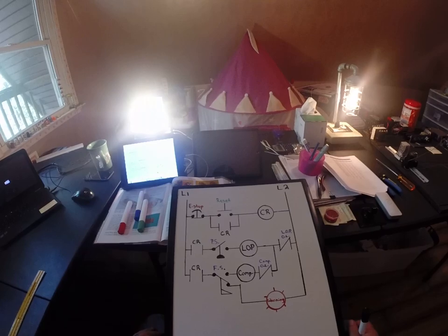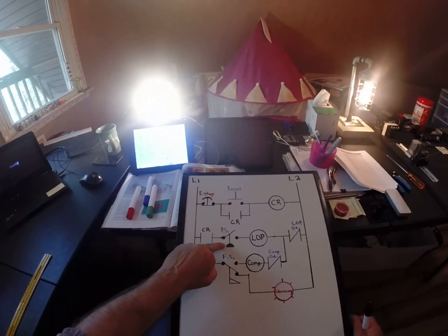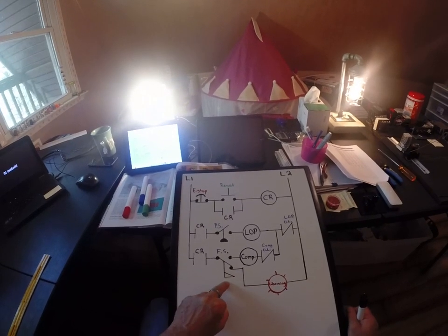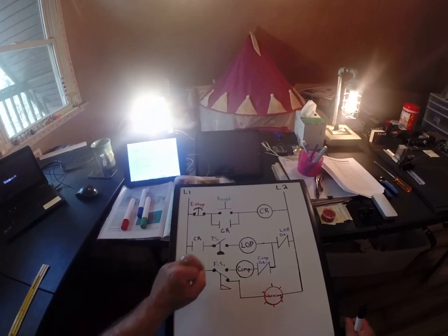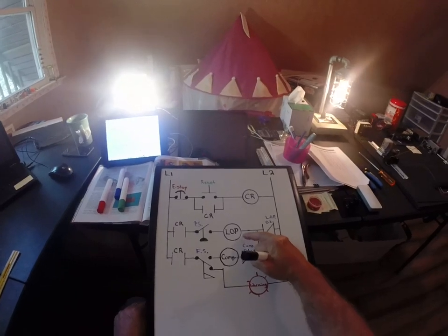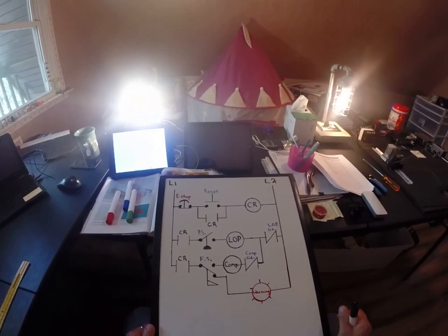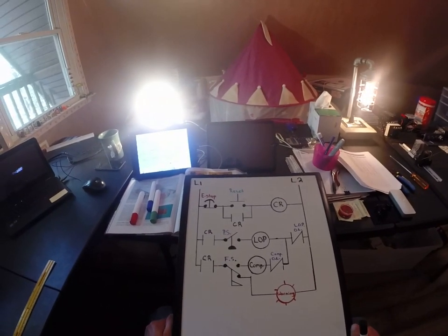This is the air compressor circuit, and as you might remember, that's a symbol for a pressure switch. That's the symbol for a flow switch. It looks like a sail, it looks like an oil can. What we have are two motors in this, a lube oil pump motor, which pumps oil into the compressor, and a compressor. So most of us know how an air compressor works.